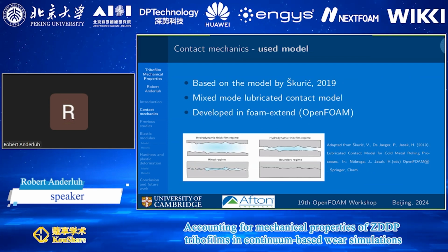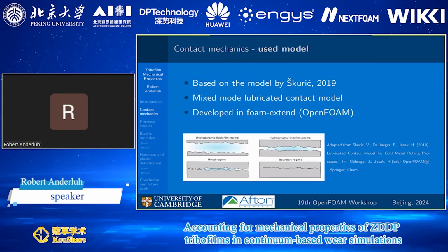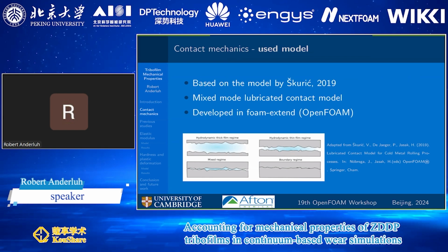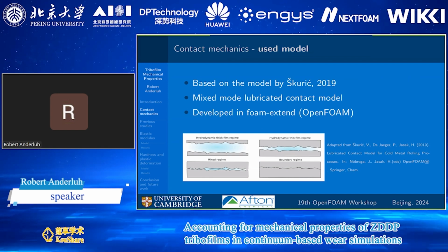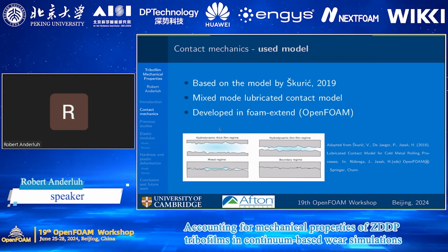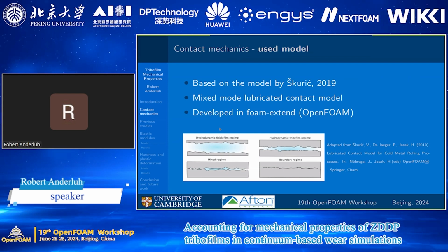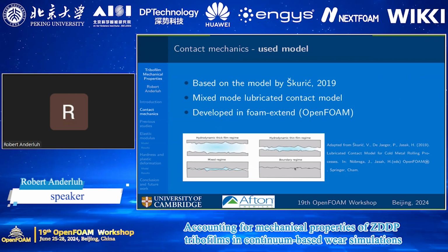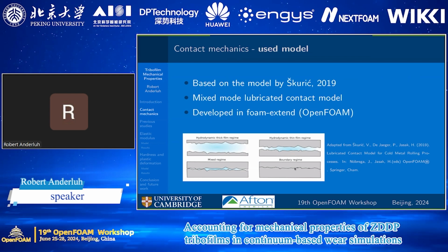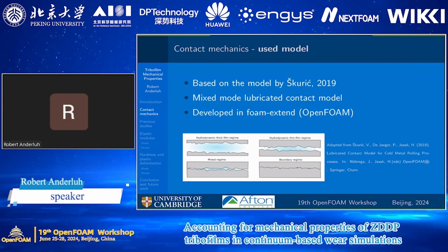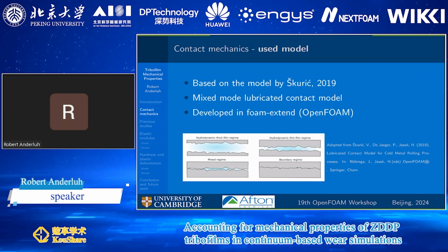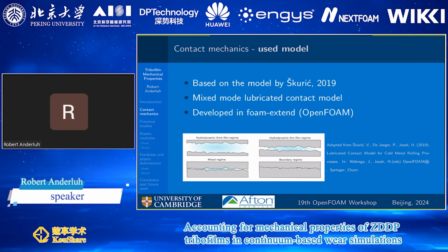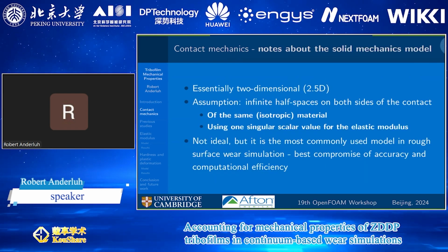Just to look at the contact mechanics model, it is essentially the same one used by Mr. Baltinen, so I don't have to go into too much detail. It's a mixed-mode lubricated contact model that is able to solve contact situations from the hydrodynamic thick film regime all the way through to the boundary lubrication regime. This is what we are aiming to use in the total ZDDP dynamic model of growth and removal.